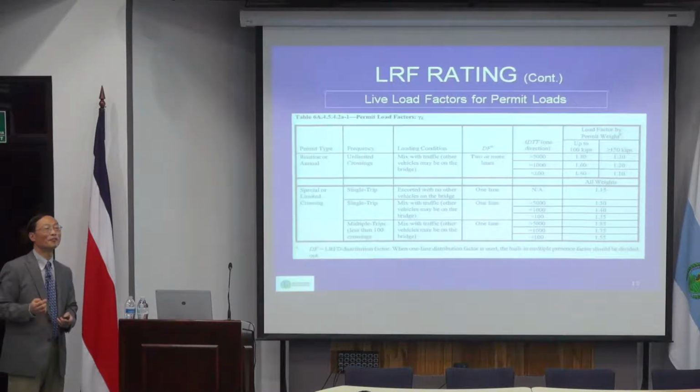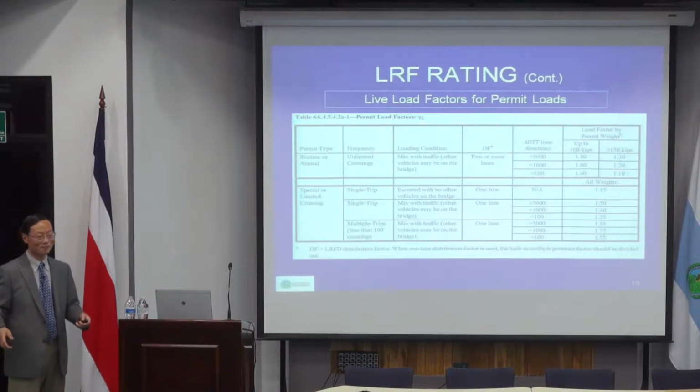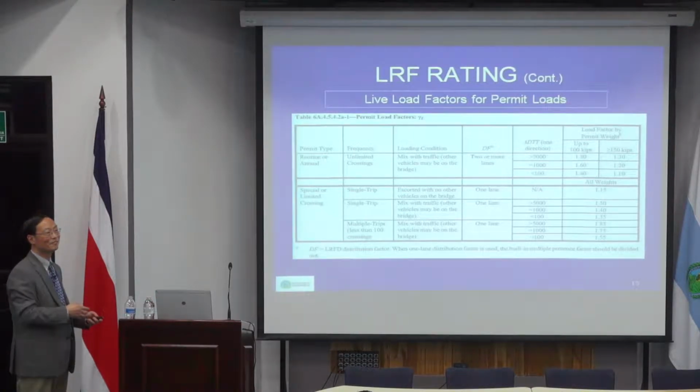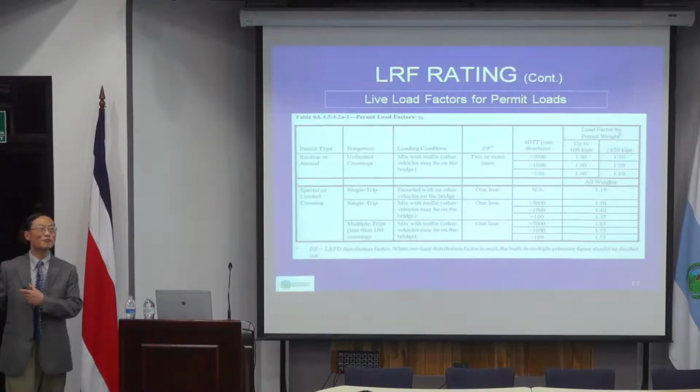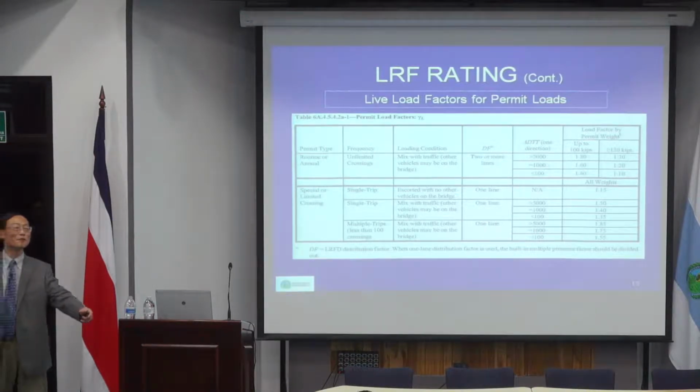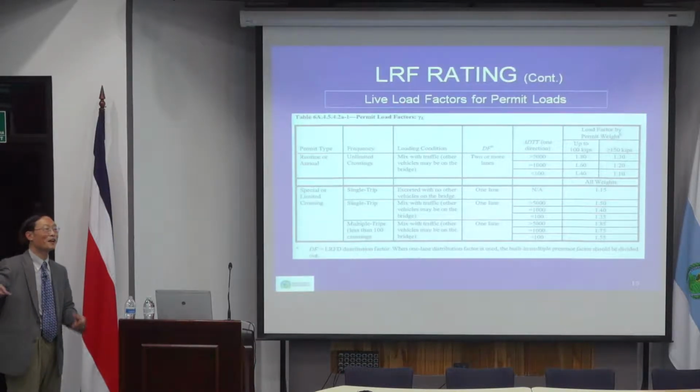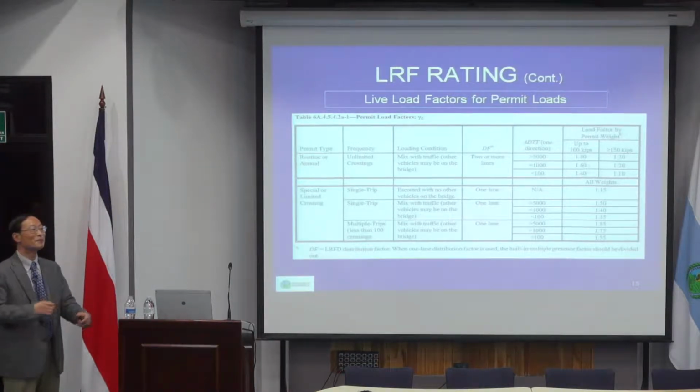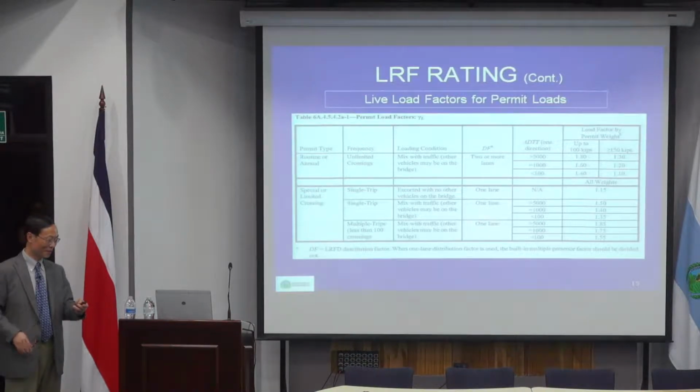If you apply for a permit load, it would really depend on whether that permit is for annual use. In other words, if I have a heavy load that I have to carry routinely, for example, if we have a transformer manufacturer around here, and the transformer is very heavy, he will have to design different configurations for the bridge, and once designed, the bridge is okay. But if he only has one transformer passing that bridge only once, then the permit is a single-use permit, and he may have less restrictive requirements, in other words, smaller load factors. And if you have to transfer every day, it's almost like a routine operation, which means an annual permit, then that load factor should be higher, almost like regular load factors.